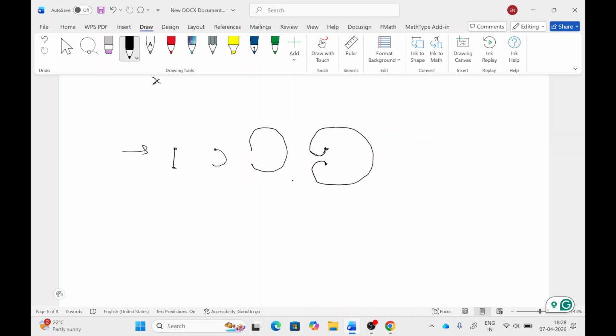The line vectors for these two halves are opposite in direction. Because of these opposite line vectors, there will be interaction between these two partials, and they will attract each other and become this type of line, and this dislocation line will detach from the primary slip dislocation line. So this is the dislocation loop generated from this dislocation line, and it moves forward in this direction.